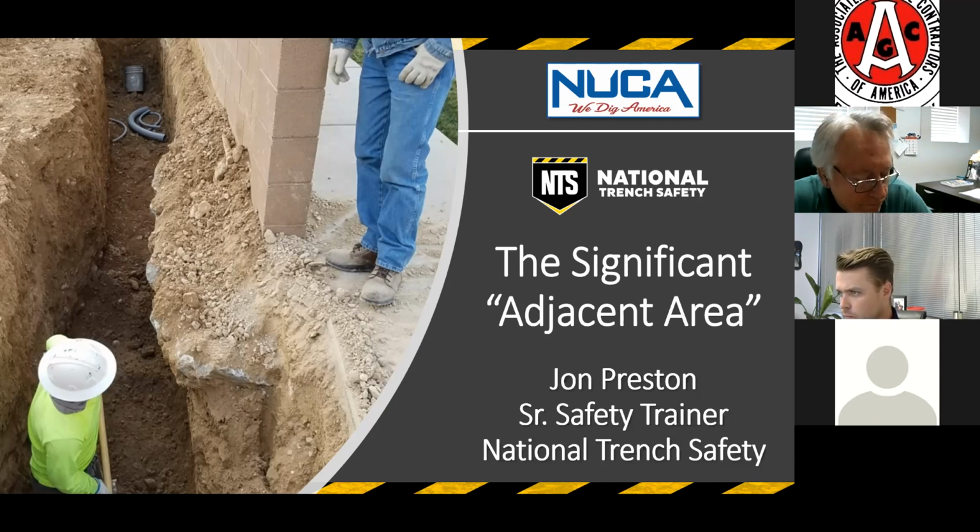So Lorenzo says a common work practice that we would employ would be to kick off the trench box at the top to prevent lateral shifting. I don't know if you want to comment back on that or not. As long as the trench box is prevented from lateral shift, I really can't comment.